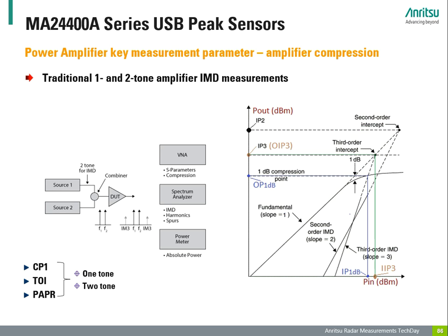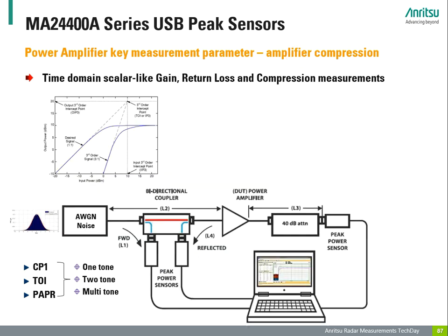For example, in case of OFDM modulation, or think about noise radar, a technology that uses noise chaotic random waveforms as transmission signal. What is the power amplifier backoff that you need to observe? What is the crest factor or the peak amplitude power ratio? You see a lot of very interesting questions.